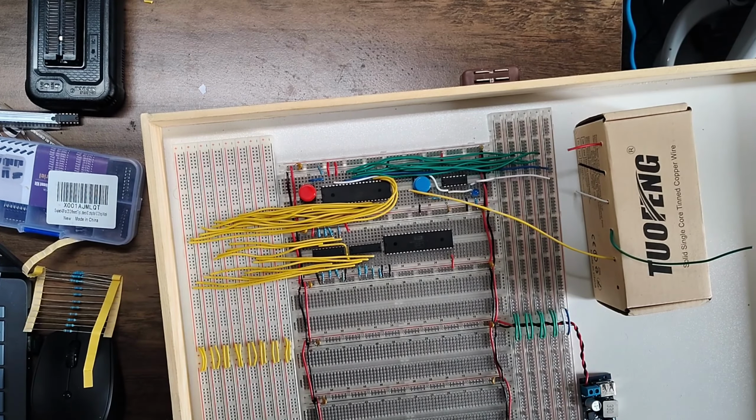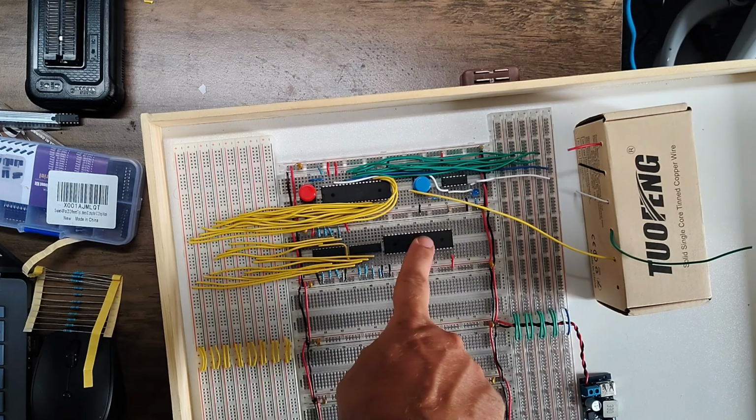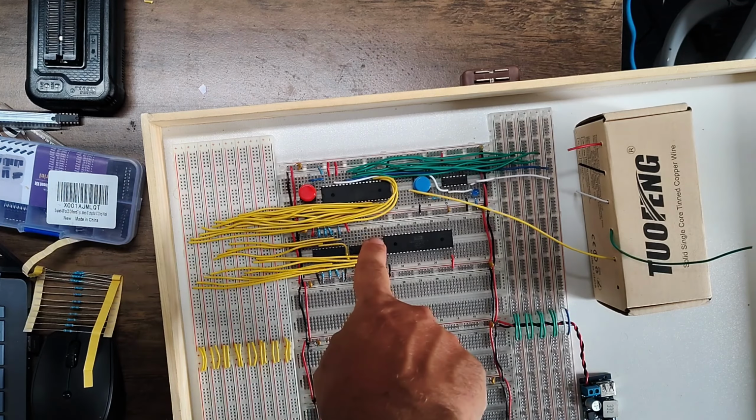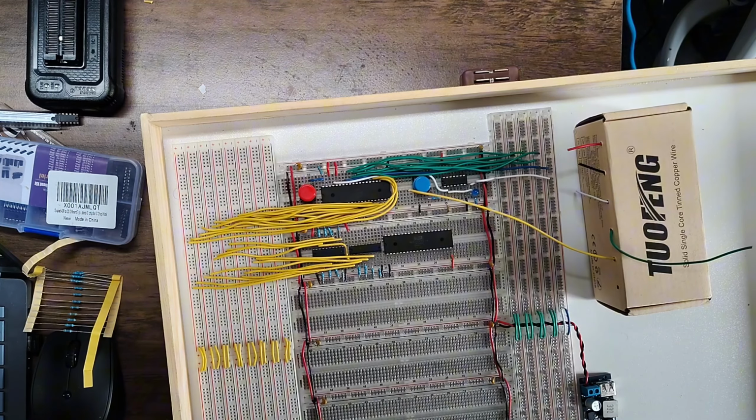And there we are. We have got the next 8 address lines tied into the correct places. Now, there's a couple more things to do before I can then move on to the interface adapter chip itself. The first thing is that we need the output from this chip to go into this chip. That's one thing. And then the second thing we will need to do is there are still 4 more comparators here that we're not using. So we have to tie all 4 of those to the same voltage, both the inputs to each other and to the same voltage. Otherwise, we won't get a proper output from the second chip. So I'll just do that now.